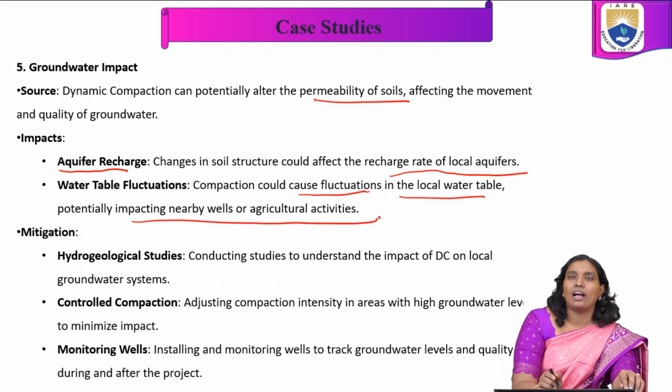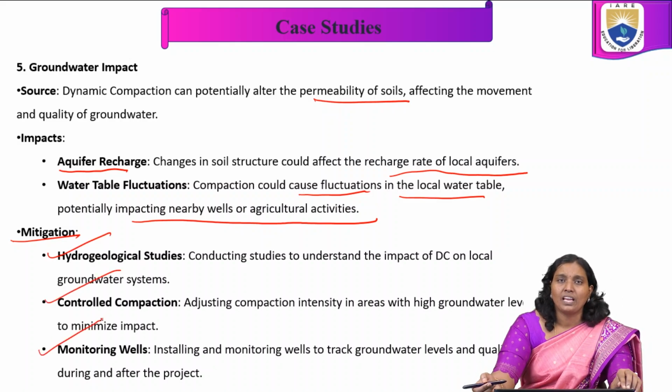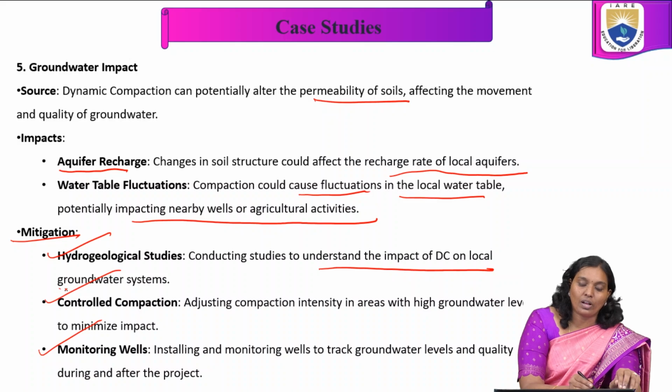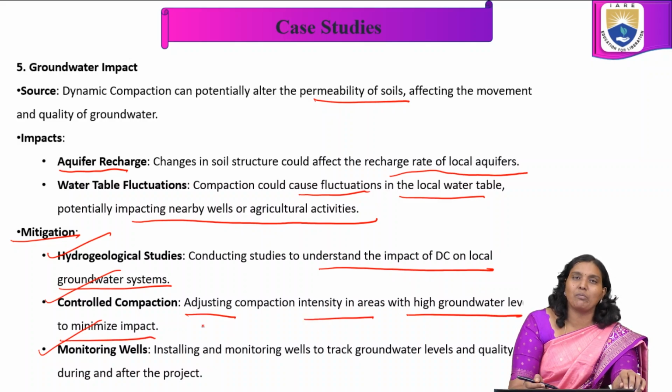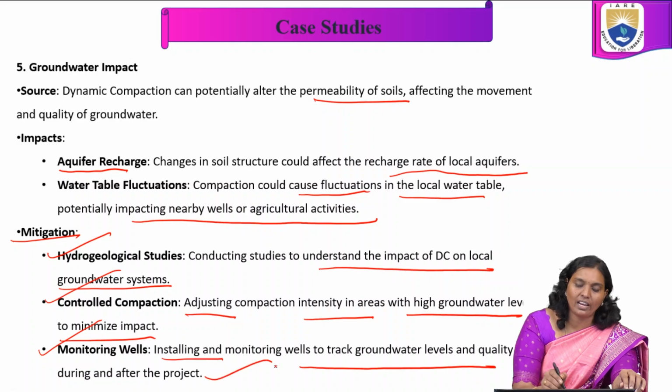wells or agriculture activities. As part of mitigation, hydrogeological studies, controlled compaction, and monitoring wells are there. In hydrogeological studies, conducting studies to understand the impact of dynamic compaction on the local groundwater system. And also controlled compaction, adjusting compaction intensity in areas with high groundwater levels to minimize impact. In monitoring wells, installing and monitoring wells to track groundwater levels and quality during and after